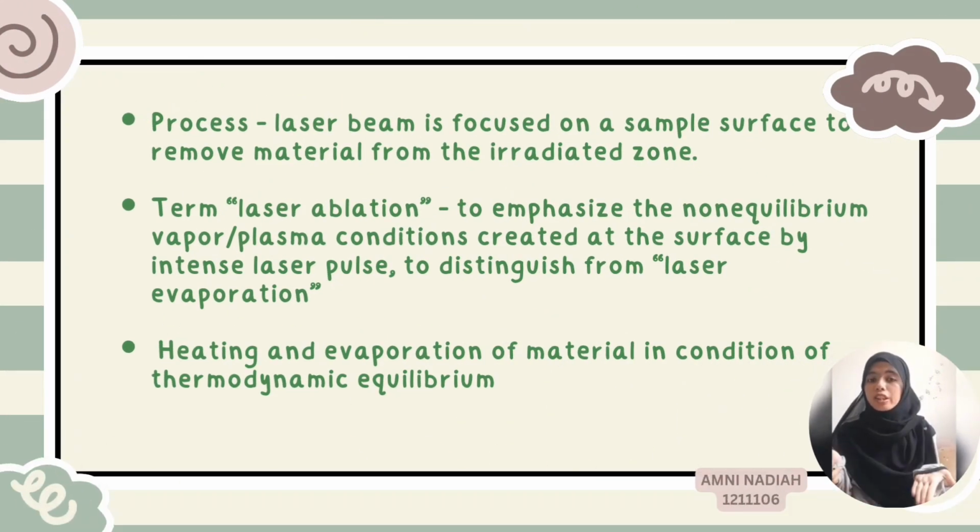Okay, now let's look at the introduction to laser ablation. What is laser ablation? Laser ablation is the process where a laser beam is focused on a sample surface to remove material from the irradiated zone. The term laser ablation is used to emphasize the non-equilibrium vapor or plasma conditions created at the surface by an intense laser pulse, to distinguish it from laser evaporation. Laser evaporation is the process of heating and evaporation of material in conditions of thermodynamic equilibrium.